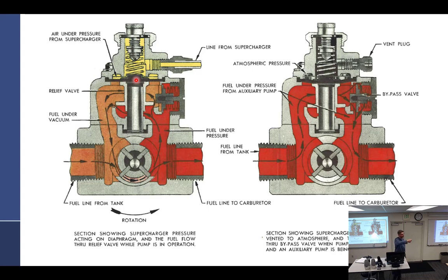If I turn it to the right, righty tighty. Think about a nut, a left-hand nut on a bolt. I got a bolt here, right? If I turn it to the right, it's going to pull the bolt on. Yes. If I turn it to the left, the nut's going to fall off. Yes. Okay, but what if it's left-hand thread? As I turn it to the left, it tightens. It's going to pull it in, and if I turn it to the right, it's going to go back out. Yes.